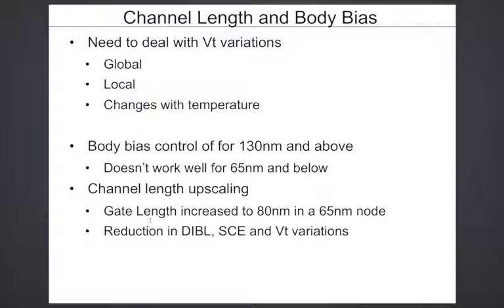Ideally, it should not have happened, but the fact of the matter is that you have impact of the channel length on the threshold voltage. You have short channel effect, reverse short channel effects, narrow width effects, reverse narrow width effects. So you have to be aware of what are the non-idealities, and actually you might be able to take advantage of this in the sizing of your transistors.